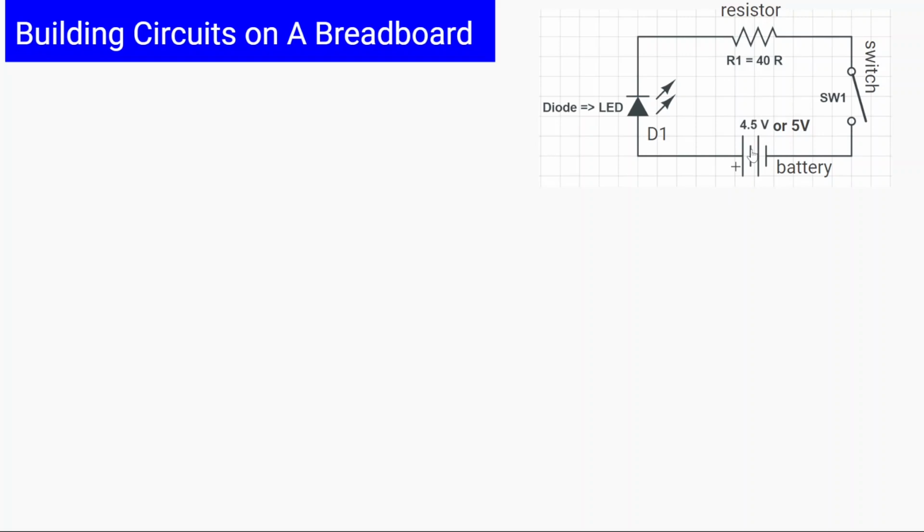As you can see here, the purpose of this circuit is simply to turn on the LED and make it glow when this switch is connected. And why is that? As you can see here, the plus side is connected with the plus side. This rectangular area with the black color for our diode is called the anode side, or the plus side of the diode, which is connected to the plus side of the battery, with a resistor to limit the current. It can have any value, 50, 100, or even 1K, it doesn't matter. So once this switch is closed, it completes the circuit, the current flows, and because the plus is connected to the plus and the negative eventually comes to the negative of the battery, the diode will glow, and that's the purpose of this particular circuit.